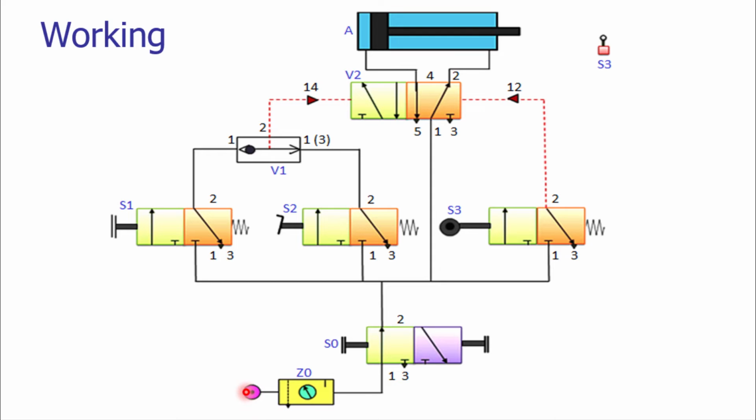The compressed air is being taken from the tank, the receiver tank, and there is the FRL unit. So this is the FRL unit. From the FRL unit we are taking the compressed air. This entire operation of taking the compressed air from the FRL unit is controlled by using a button switch, a button operated valve.